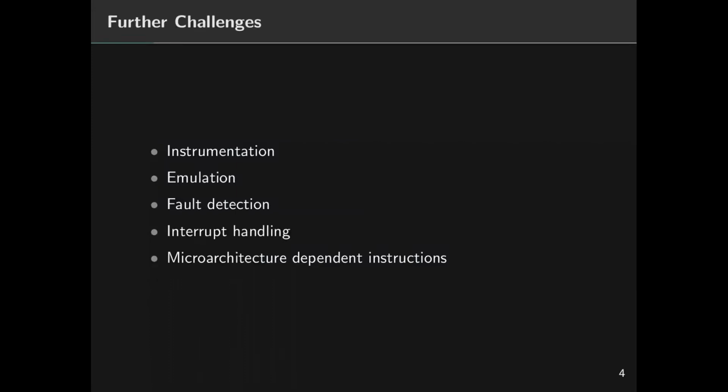And there are even more challenges which we are facing in comparison to desktop systems. Binary analysis on desktop systems normally makes great use of instrumentation. So it instruments the software under test or under analysis to add certain hooks or address sanitizer checks, for instance, during runtime to verify that everything is going fine. On embedded devices, this is challenging for two reasons. Once again, the missing abstraction of the operating system, and furthermore, quite often the code only resides inside the read-only memory of an embedded device.